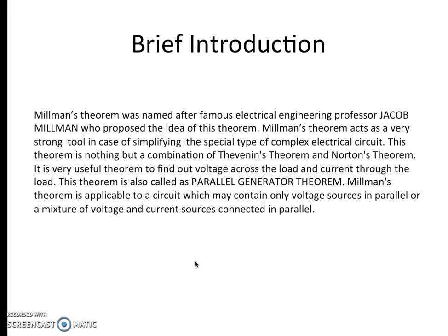It is a very useful theorem to find out the voltage across the load and the current through the load. This theorem is also called the parallel generator theorem. Millman's theorem is applicable to a circuit which may contain only voltage sources in parallel, or a mixture of voltage and current sources connected in parallel.